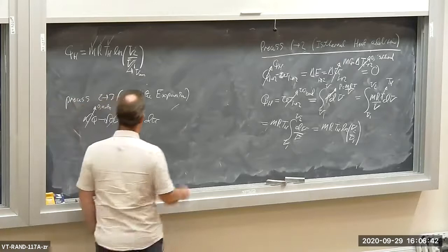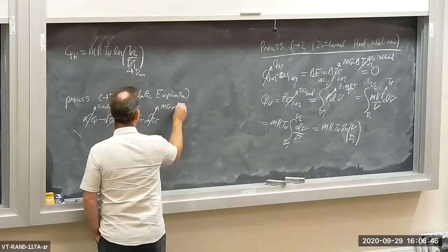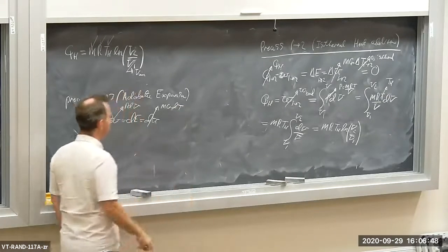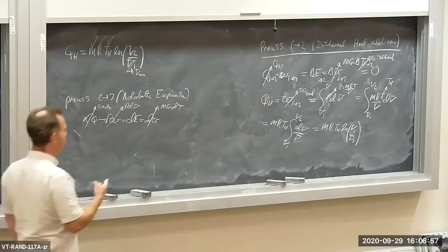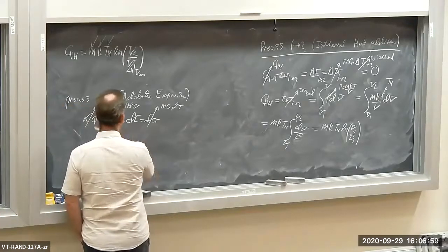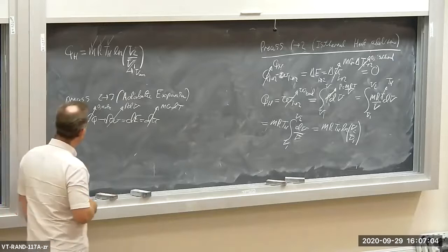Now, if we assume constant specific heats, then dU is equal to mCV dT. That's from the property relationship. That's internal energy, not specific internal energy. Notice everything's capitals in here. Okay, so let's write what I got.